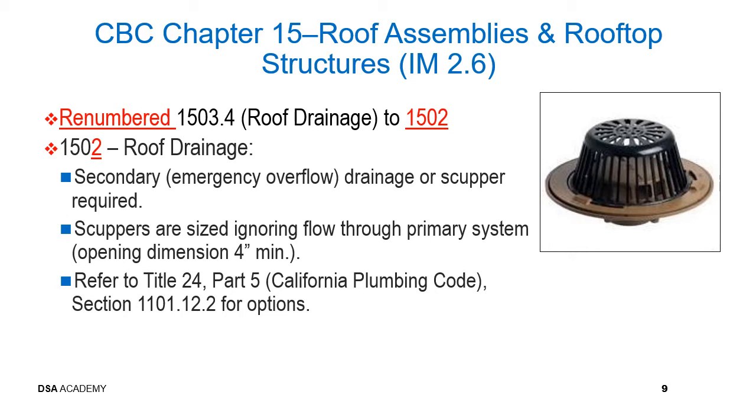Secondary or emergency overflow drains or scuppers shall be provided where water may be entrapped. CBC Section 1502.3. Scuppers are designed without considering the flow through the primary system. The opening dimension shall not be less than 4 inches.